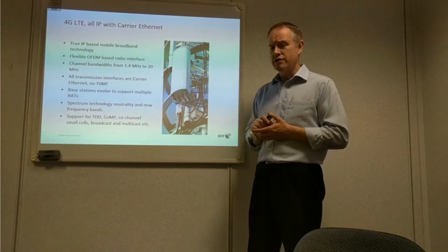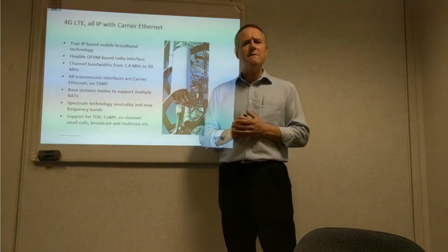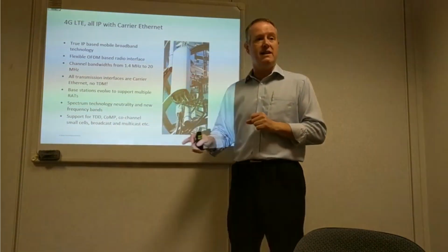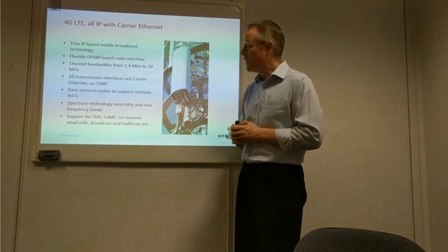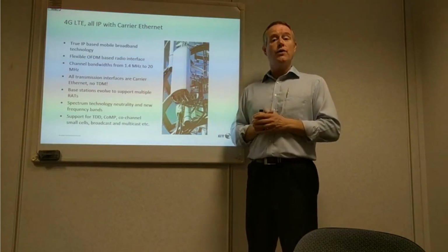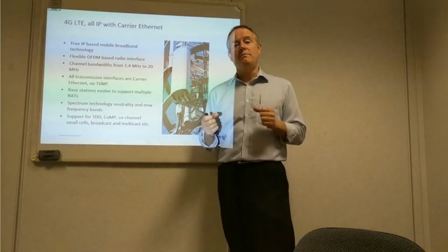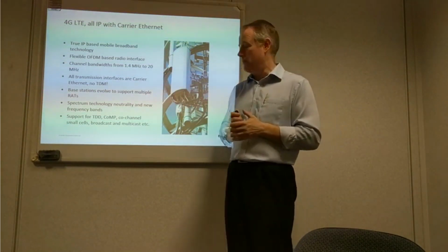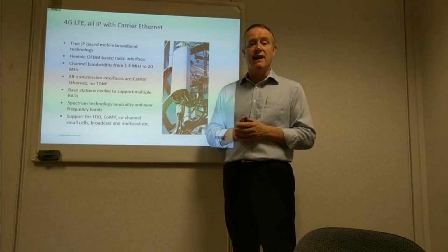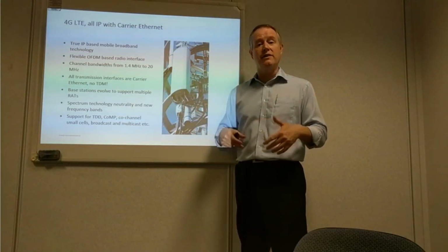But actually we've also got support now for time division duplex in 4G. Now there was TDD spectrum in 3G, but it was never deployed for a number of reasons. So the first time we really come across TDD, certainly in Western Europe, is with the introduction of 4G. We've got techniques such as CoMP, coordinated multi-point transmission and reception, where we need to guarantee time alignment between base stations to get coherent reception on a mobile device. We have co-channel small cells that need techniques such as enhanced inter-cell interference coordination. And we've got broadcast and multicast technologies as well based on eMBMS.